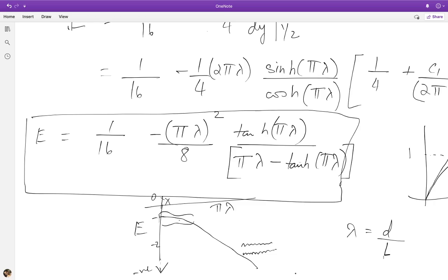So with this in mind, you can also approach problems involving surface roughness, which could be this problem as well. I would just have to write an arbitrary surface roughness as a sum of various sinusoidal components, which I can do in general using a Fourier series or a Fourier transform. And then because the entire perturbation calculation is linear, I can add up the solutions to the different sinusoidal wavelengths of the wall to get the total solution for arbitrary surface roughness, which is why it's also useful to consider the sinusoidal form of the waviness of the wall. So what we've done is not specific only to a sinusoidal form. You can represent any solution to any form of roughness within the domain perturbation method. And of course for creeping flow where the equations are linear.